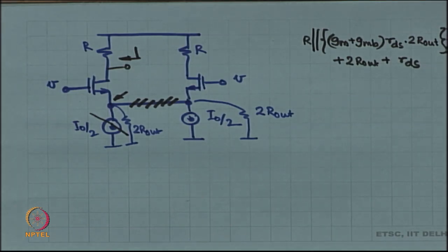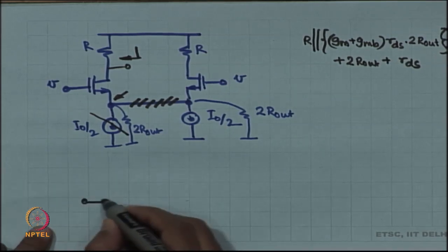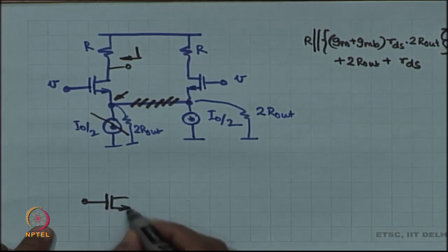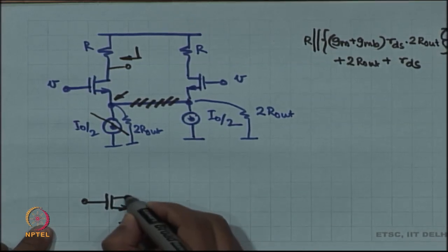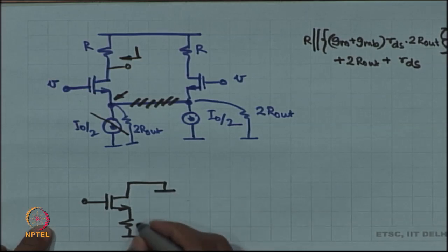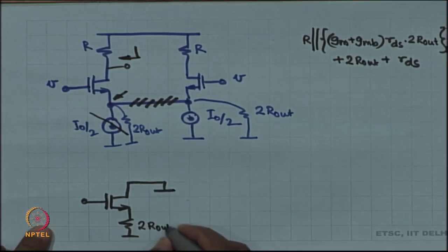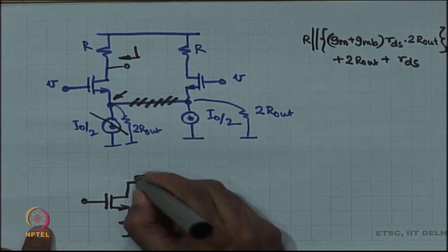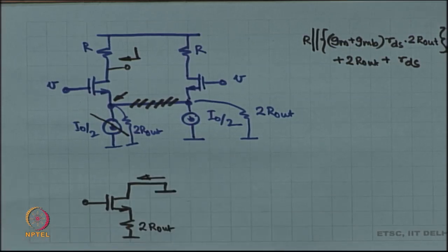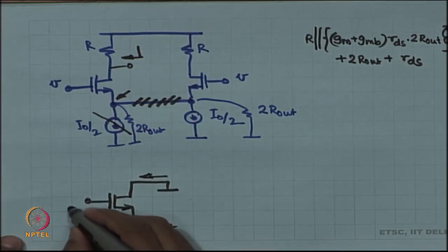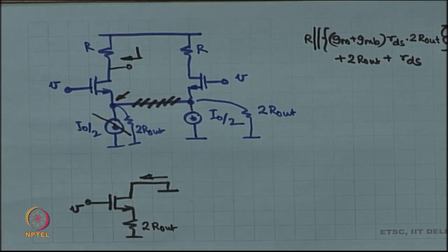And then in the next step, you also have to find out the short circuit current. Now, when you go to do the short circuit current, this is really your experiment. Okay, you are trying to measure this current. You apply a voltage V, try to measure the current.